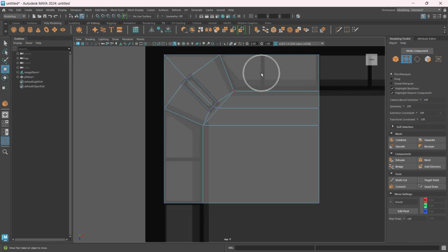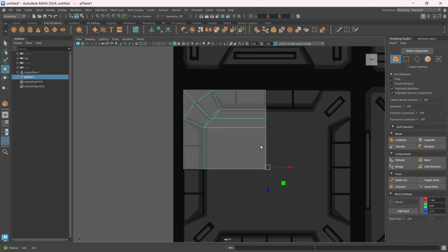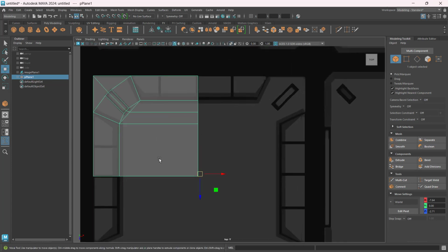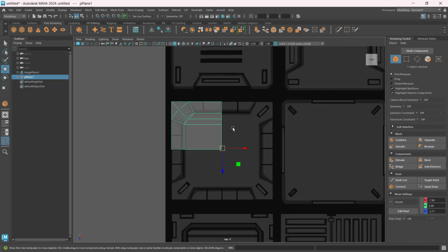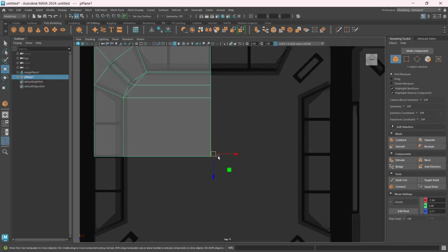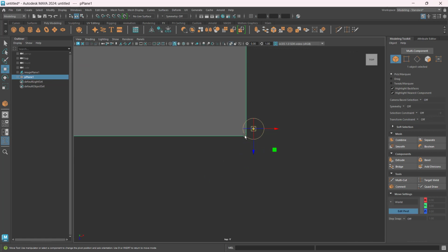This I have a different plan, okay? But let's say I have this. Now to do a duplicate special on this, and since it's going to be done at least 3 times, the thing that I will do is first I will position my gizmo where the duplicate special is referenced. So that means if I do a duplicate special, it will start where the gizmo is. So I better position the gizmo properly.